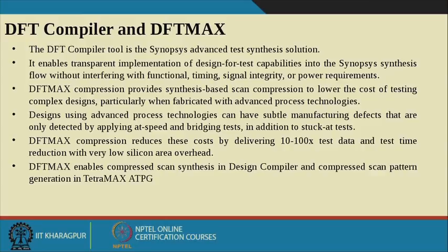So DFT Max enables complex scan synthesis in Design Compiler and complex scan pattern generation in TetraMAX ATPG. So what is the usefulness of this DFT Max tool? As I said, it can reduce the cost by a huge amount, providing 10 to 100x test data compression.